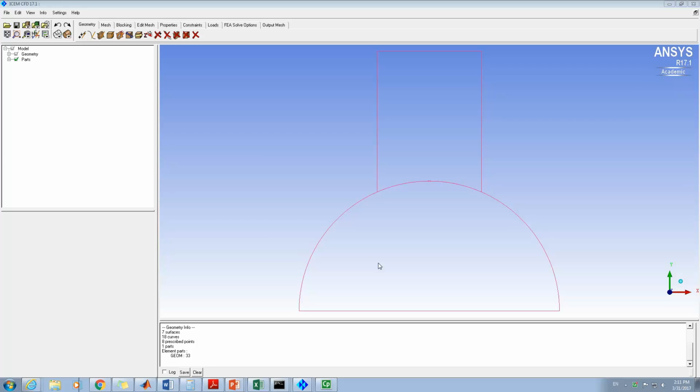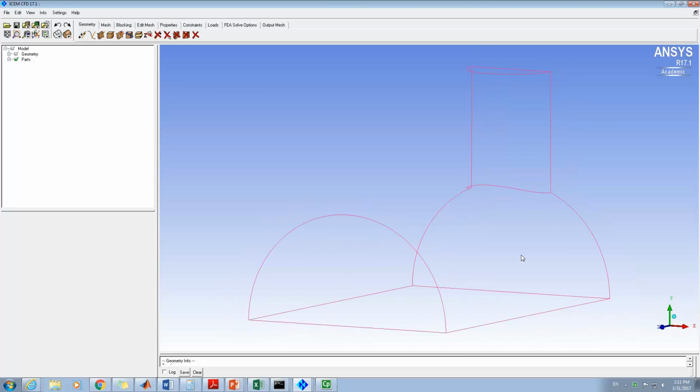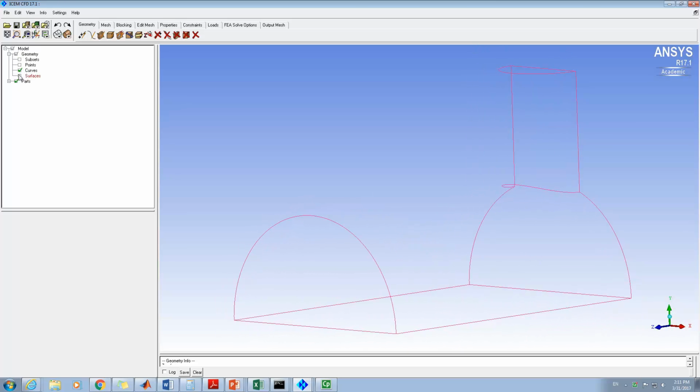Okay, in this video, we will show how to create an unstructured mesh and how to create a hybrid mesh. An unstructured mesh is especially useful for complex geometry, because for such complicated geometries, we probably have difficulty creating the corresponding blocks and then associating the blocks to the geometry, right? So in such cases, we can simply use the unstructured mesh. For example, for this geometry.